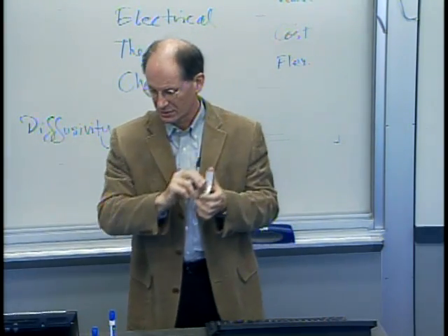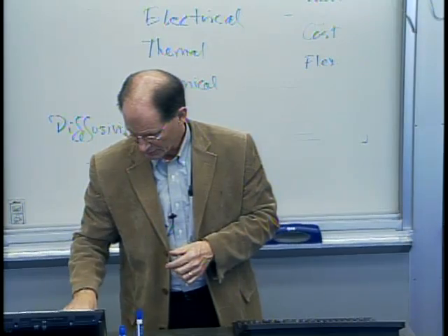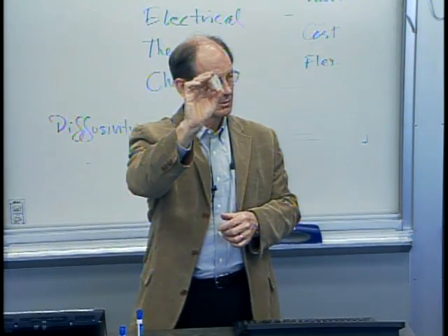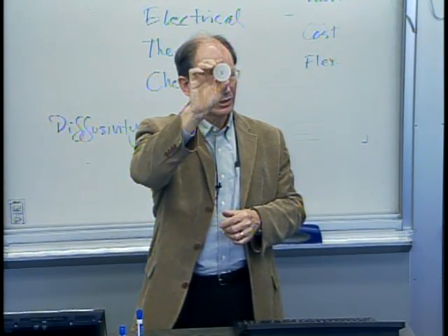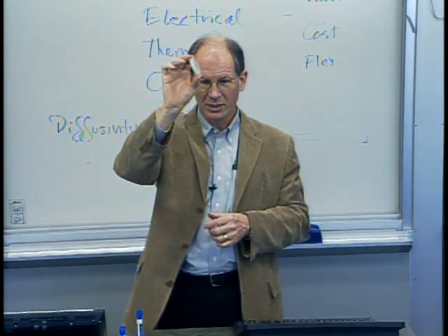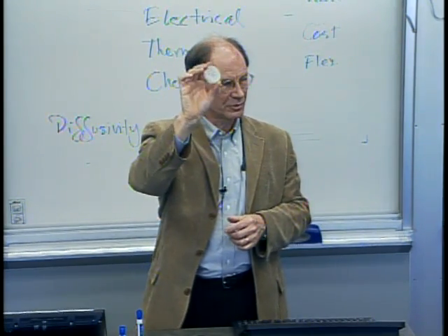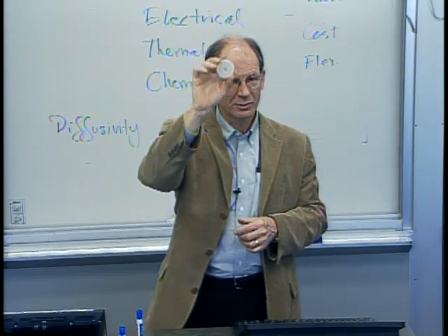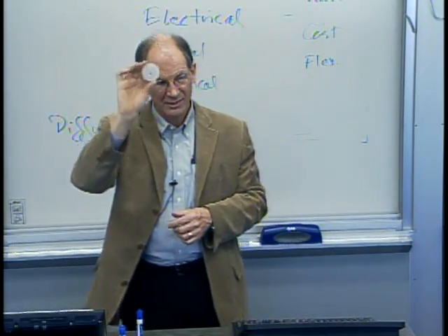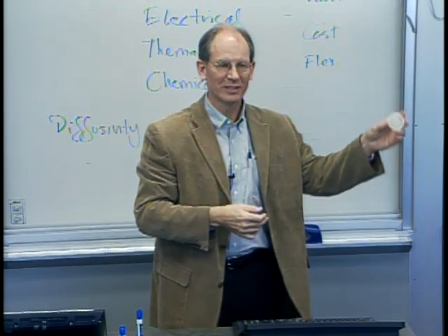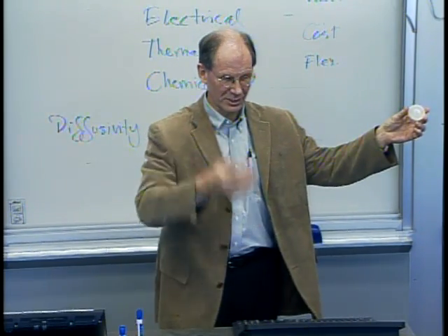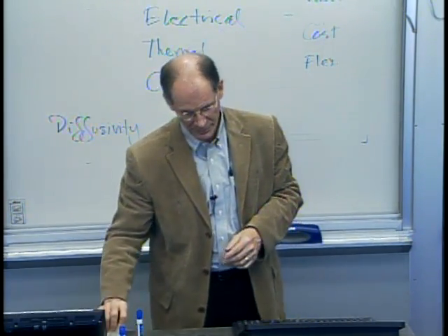What stresses and strains did it have? Same thing with this. I needed to know what the characteristic of the polymer was. How did it react to temperature? What was its viscosity with temperature? What are its heat transfer characteristics? And then I needed to know what temperature it was, what pressure it saw, and what the heat transfer characteristics of the mold were.